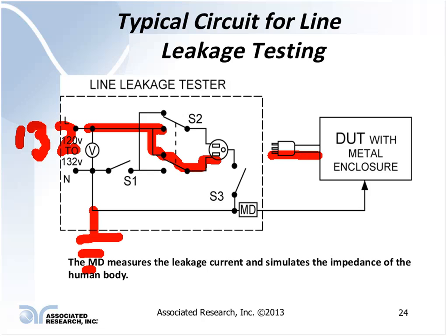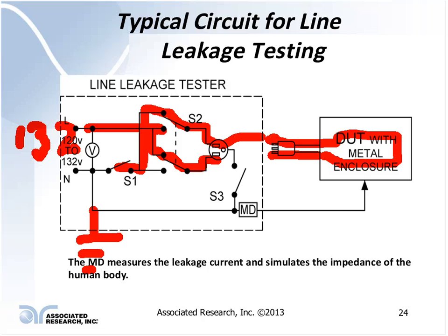Okay. So my device should be sitting on a non-conductive surface where it is not in contact with earth. Otherwise, my measuring device would be essentially shorted out. So now I have 120 volts feeding into my product, going through all the circuitry in the product itself. This is sitting at 120 volt potential, feeding back into the other side, which comes up to my switch, which is open.